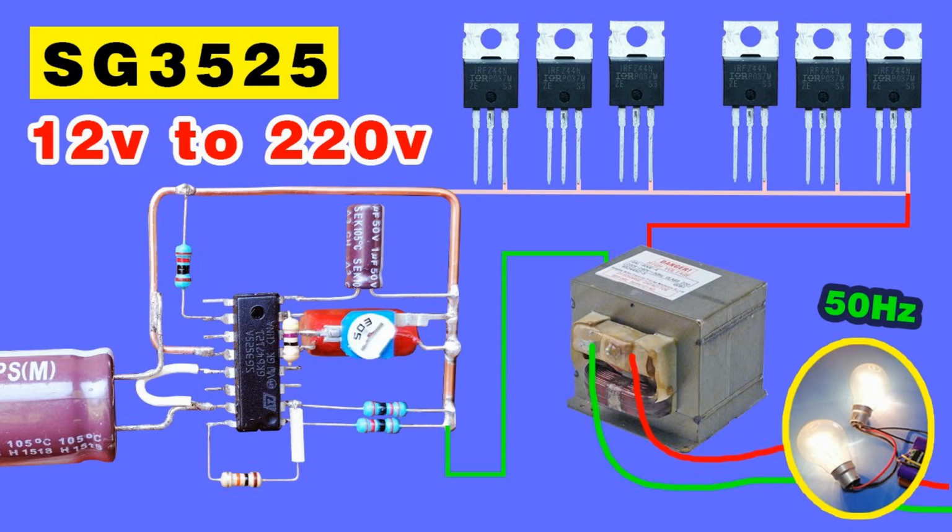Low on resistance, RDS(on). When turned on, MOSFETs exhibit very low resistance between the drain and source terminals. This low on resistance minimizes power dissipation and heat generation, which is crucial for efficient power management.